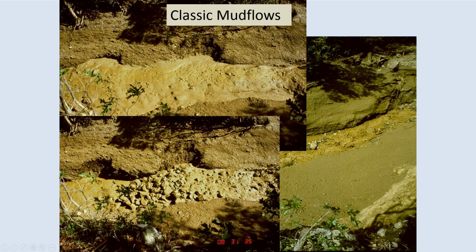Typically, there is a frontal wave associated with it, although the frontal wave may slow the movement down a little bit until the peak catches up with it. The frontal wave doesn't play a significant role unless there's very little volume in the entire event. It does play a significant role in the propagation and progression of the flow past the alluvial fan apex and on downstream.